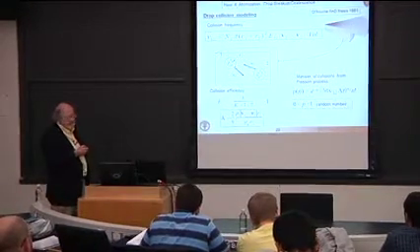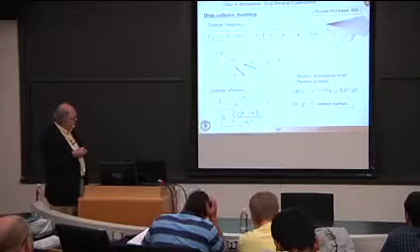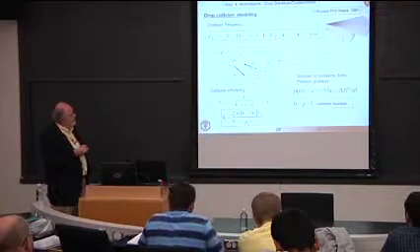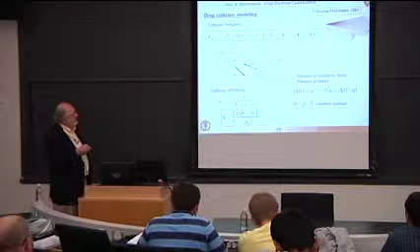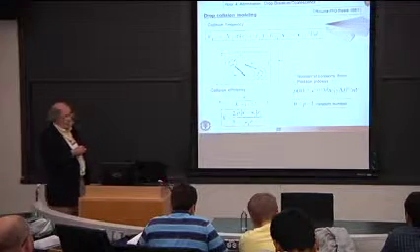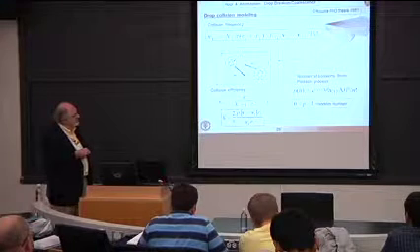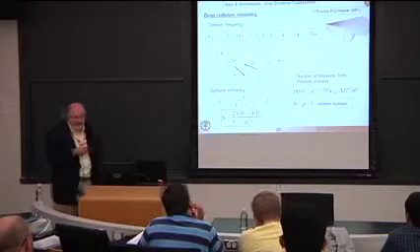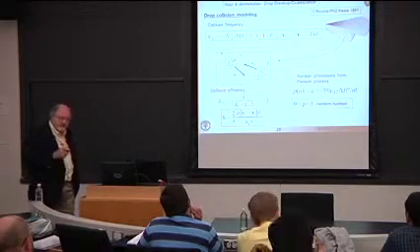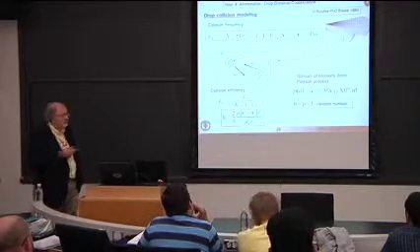I want to calculate a collision frequency between drops in parcel 1 and parcel 2. I know how many drops there are in parcel 2 here, let's say. I also know the effective collision diameter. So basically, knowing the radius of drops in parcel 2 and in parcel 1, I can calculate, like we do in kinetic theory, knowing essentially the collision cross-section of two molecules.